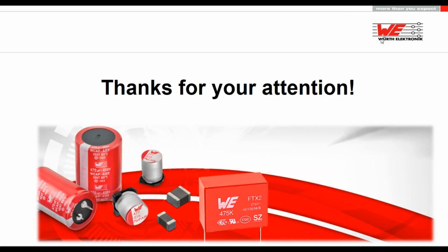A very good question on the DC bias, how to take care of the DC bias. In case of rated voltage, normally you should overdimension the rated voltage of a class 2 ceramic.